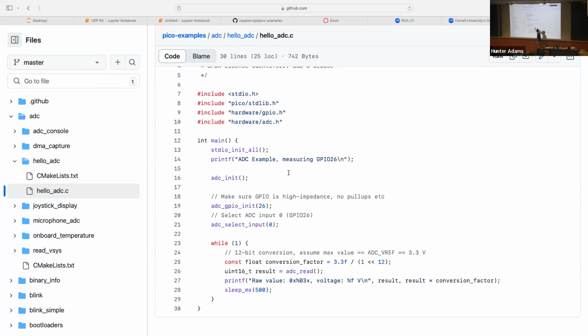And once you have that set up, for purposes of lab 2, the ADC is ready to go. Every time you want to gather a sample off the ADC, you simply call ADC read, and that will give you back an unsigned 16-bit short, a uint16. It's going to be some number in the range of 0 to 2 to the 12th, because this is a 12-bit ADC, right? So you'll get some number in the range of 0 up to 4097.